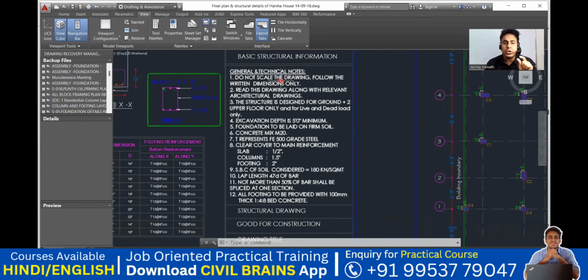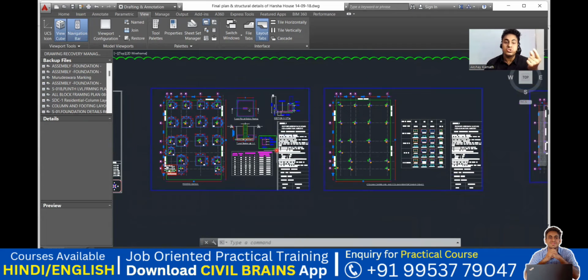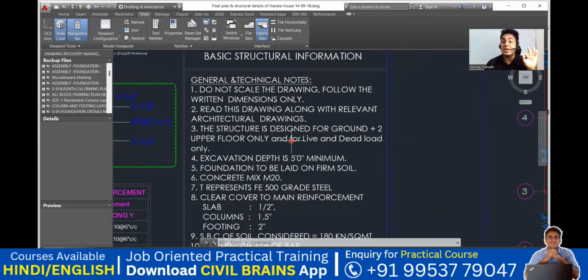These are the basic points they write. That is, do not scale the drawing, follow the written dimensions only. Read this drawing along with the relevant architectural drawing. This is very important. The structure is designed for a ground plus 2 upper floor only and for live load and dead load only. That means this particular structure has been designed only for ground plus 2 story. That is ground floor, first floor and the second floor. And we cannot put another floor over that.